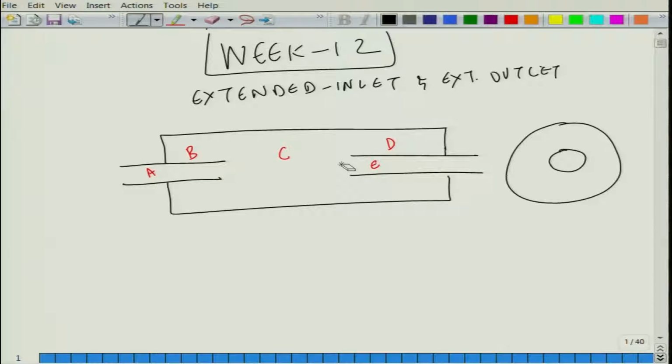All this while, ever since we presented the system in week 4, we have been considering only planar wave propagation. To accommodate the higher order mode effects, we used to incorporate end corrections, with the notion that the physical length, let us say L1 here, and this is L2, the physical length. These end plates are rigid, so this annular plate is rigid.